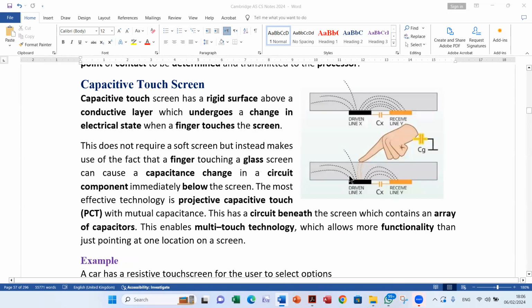There is another technology used with touch screens. This is called capacitive touch screen, where your finger acts as a conductor, and when it touches the surface of the screen, some electrons jump into your finger, or the electrostatic field is modified by the touch of your bare fingers, and there are sensors that detect that disturbance in the charge, and then the touch is registered.